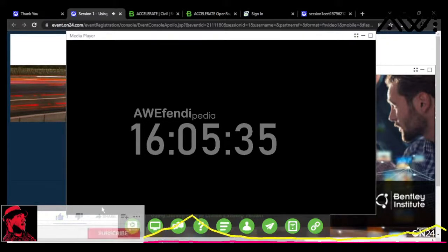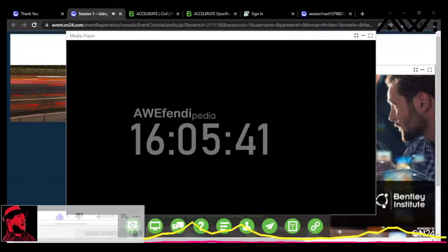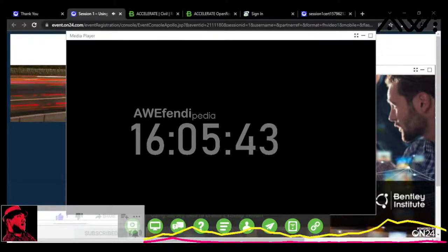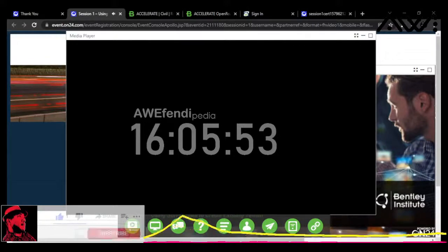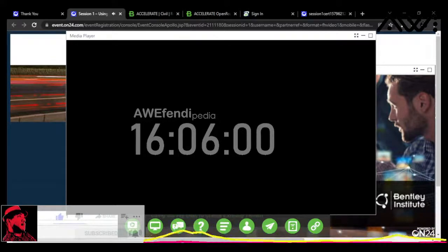In this batch of files, we have some duplicate point features. If the same point name is collected maybe from 2 different setups, it warns you and says, hey, we found a duplicate point. What do you want to do with it? What's cool is we have this differences tab here. I can look and see, is this a completely different point that they shot and I just need to rename it, give it a new name, or are they actually shooting the same point? So I can compare what was first imported and what was imported second.